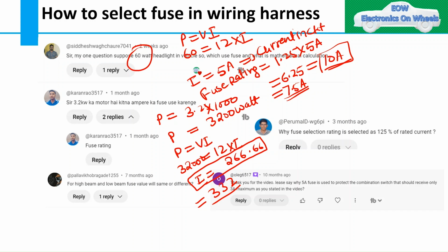Sometimes what happens in mega fuses or midi fuses, you will see in this particular case that OEMs are using 300 amps of fuse itself, or 350 in some cases. The reason is that it is a very high current, and we are not taking directly that particular factor. So sometimes in these mega fuses we take the factor of 1.10 also.